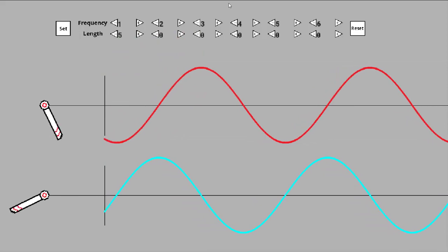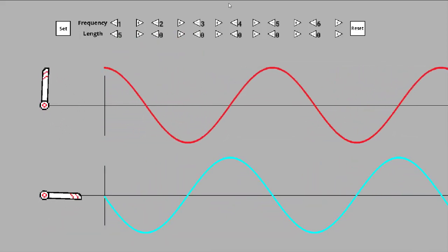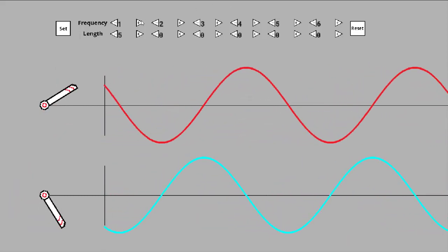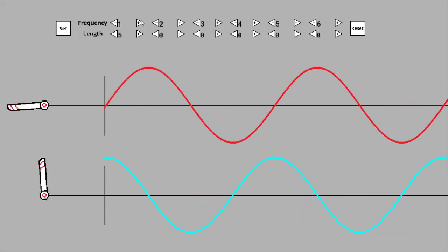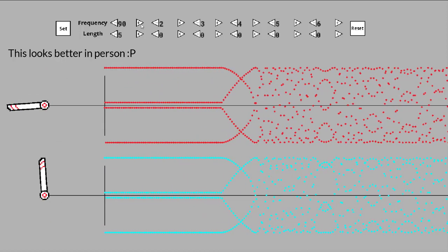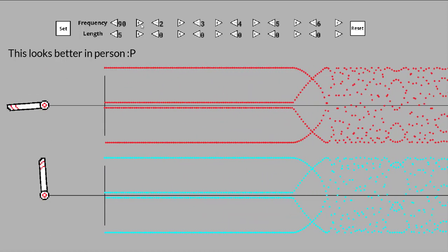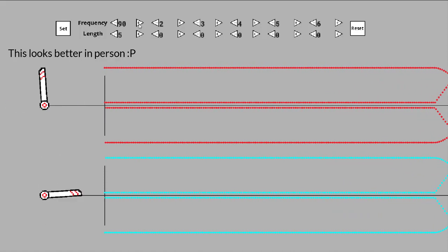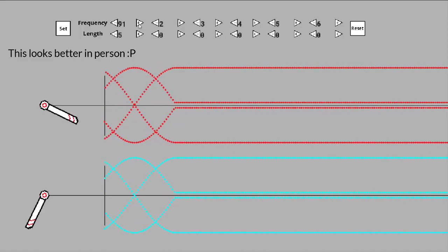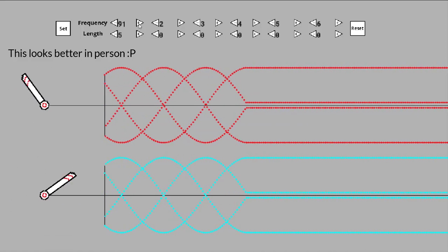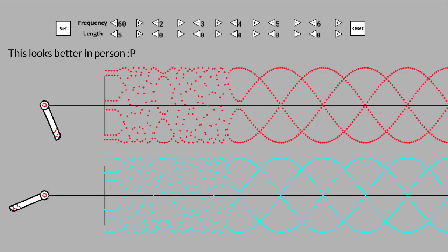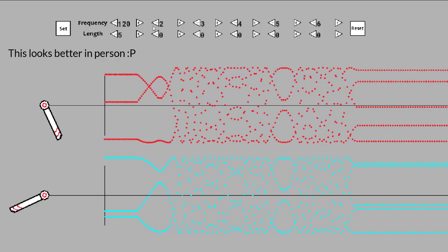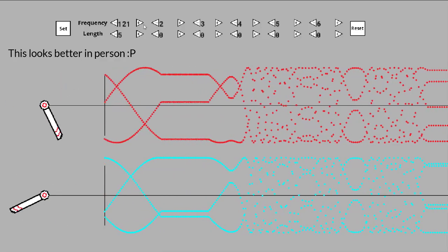The last example is a byproduct of the frequency directly mapping to how many degrees it shifts each frame. If we increase the frequency high enough, we'll start to notice some interesting behavior at a few key frequencies. At 90, we'll see an interesting aliasing effect where it looks like we're seeing the fundamental as 4 stationary phasors. Changing the frequency by 1, we'll see each of those copies rotate around as if they were rotating with a frequency of 1. And we see a neat spiraling effect on the plot. This happens at 60, 72, 90, 120, and pretty much any even division of 360. It's just another neat effect to play with.